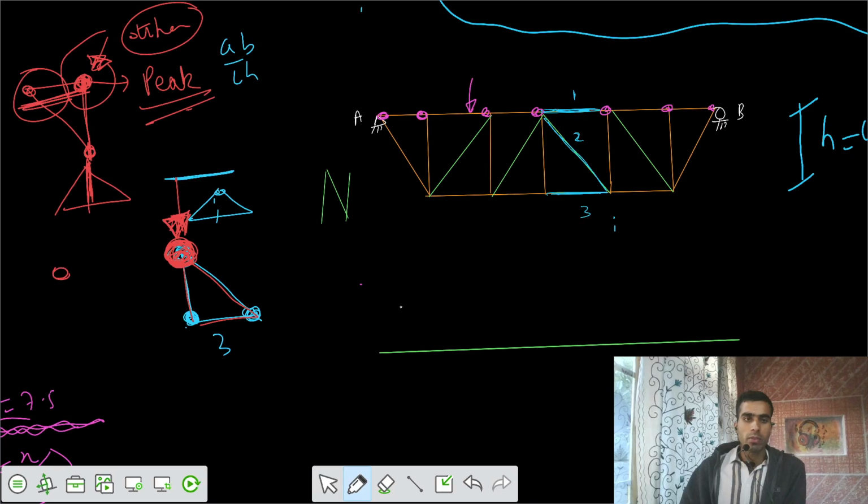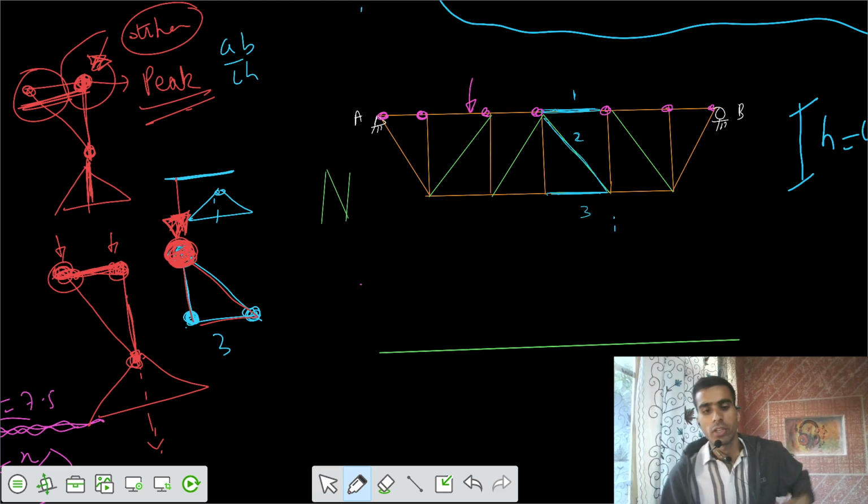But for the previous one, we said two joints are critical. I said the joint peak would be developed at this location. Because of that, if you have two loading joints, then for the third one, if it's on the same line, the peak gets developed at that point. But for this one, you have to check that. Also, you can check that by the equation.